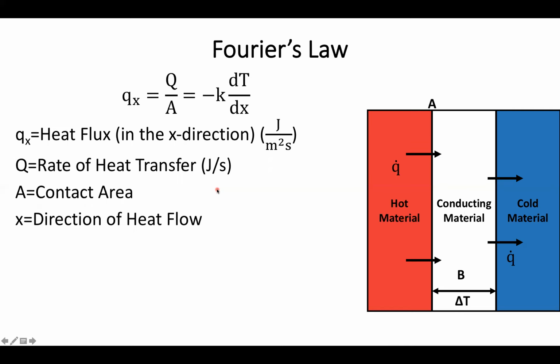Now we're mostly going to be looking at this heat transfer in a one-dimensional sort of perspective. You can develop this into a multi-dimensional model, but it's often done by looking at each dimension individually. So this is actually a pretty good place to start. So we're going to be typically describing everything in the direction of heat flow, with our direction of heat flow being in the x direction, and the larger the x value, the greater the distance the heat has to travel, which is going to be specified as dx, or delta x in a non-infinitesimal fashion.